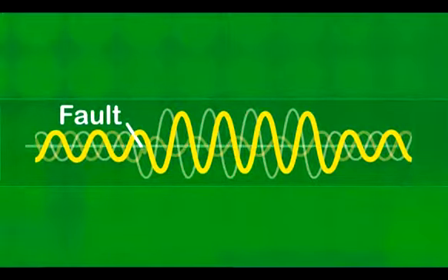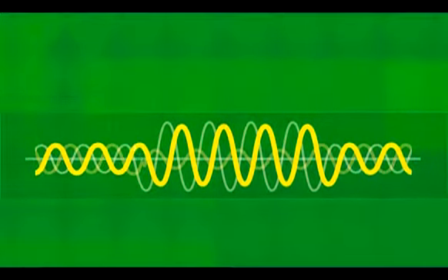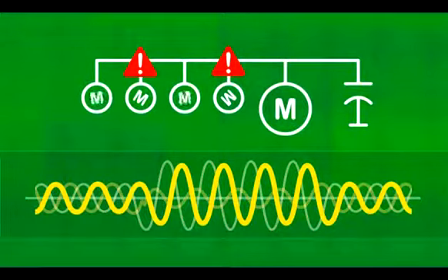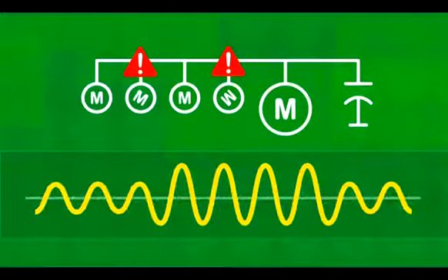Certain fault conditions can produce voltage swells on the unfaulted phases. Swells can also be the result of de-energizing large loads, load shedding, or energizing large capacitor banks. This figure shows the waveform of a voltage swell event.